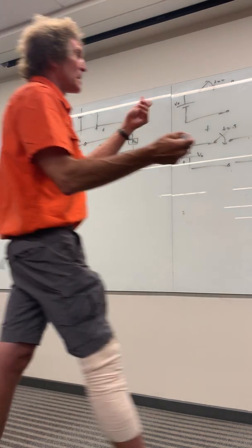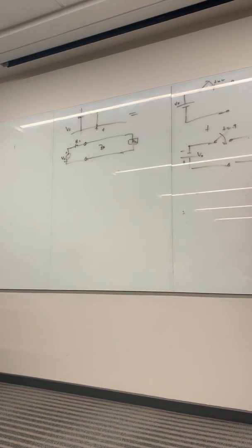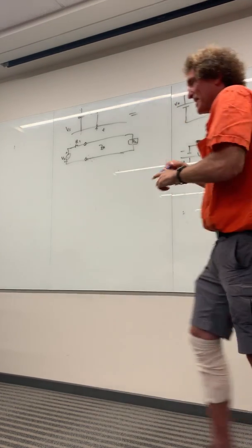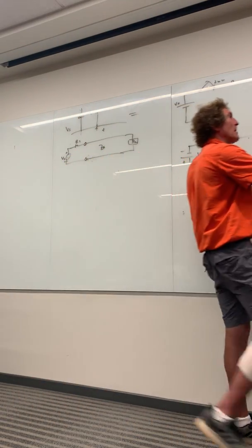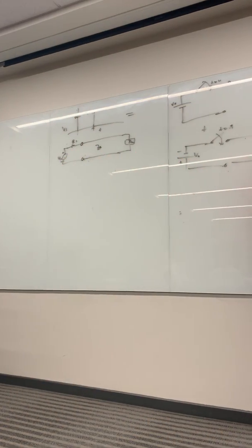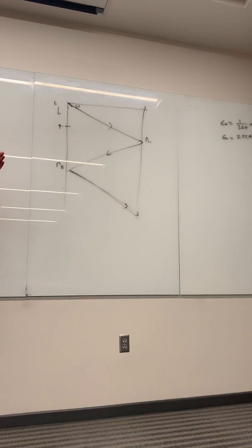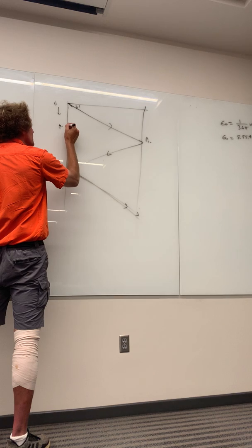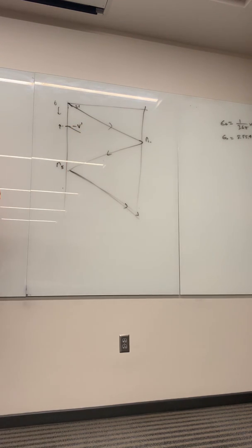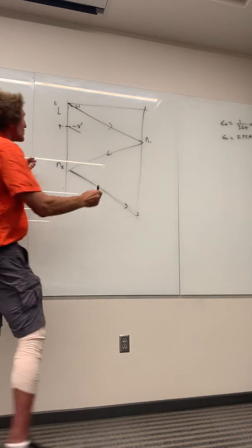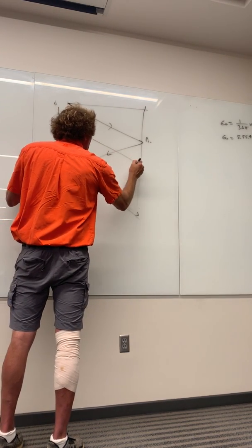Then he comes down to the point tau. All right, that's a good try. He comes down to the point tau, right? This is the time delayed tau. Follow me? Now he draws the same exact bounce diagram, but instead of V prime, it's minus V prime. Follow me? Because now the voltage on the line is the same magnitude, opposite sign. All right? And then you just draw that, like so.